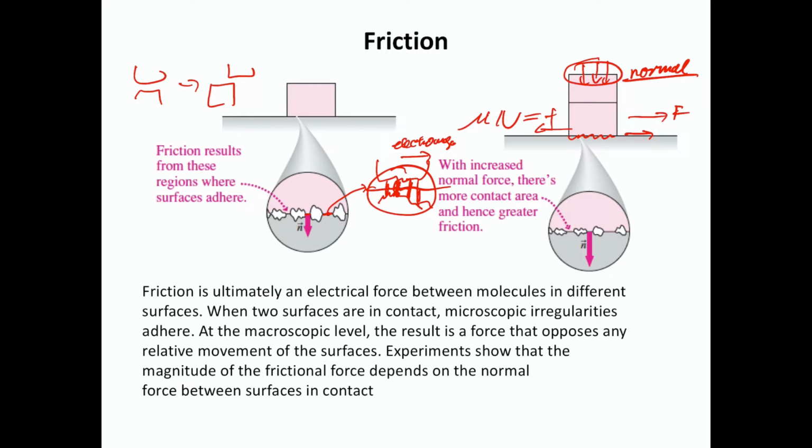Now, look at how he measures. He measures with the spring balance, trying to drag this one along at a sort of constant speed. It's a rough measurement, but it does illustrate the physics. The pull force must equal the friction. This is how we can measure the friction.